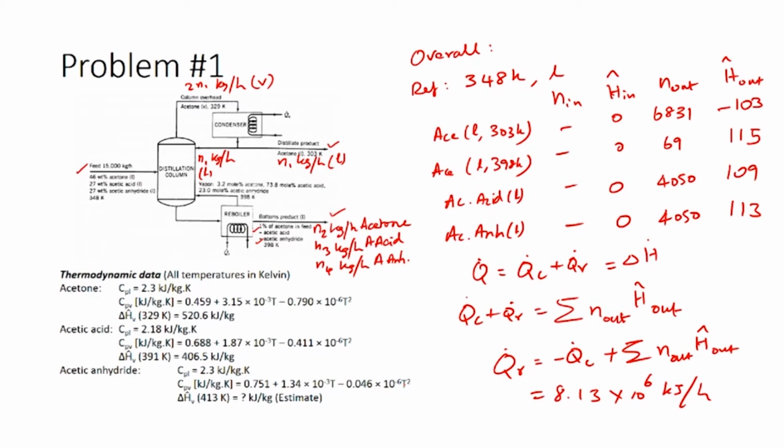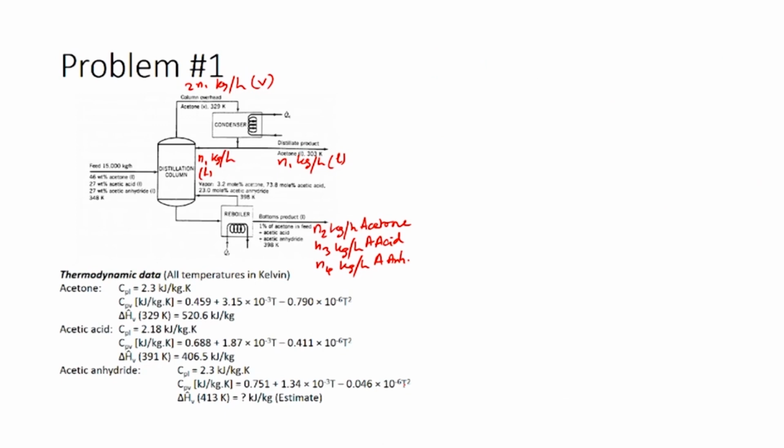So, using the heat of vaporization for steam which is saturated at 10 bar, that can be obtained from the steam tables, we can calculate how much would be the mass of steam which is required for generating that amount of energy. So, just by condensation, using the steam tables we can identify the enthalpy associated with condensation or vaporization of saturated steam at 10 bar as 1999 kilojoules per kilogram, and so this means condensation of 1 kilogram of steam which is saturated at 10 bar would generate close to 2000 kilojoules of energy.